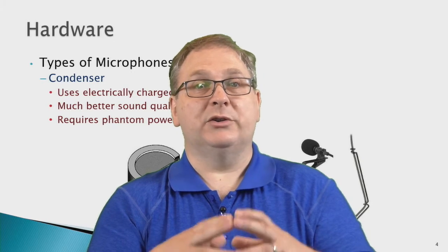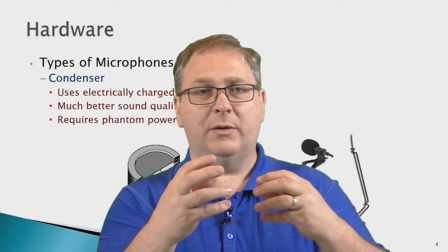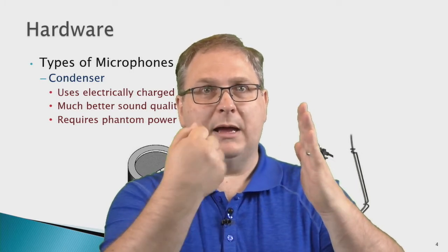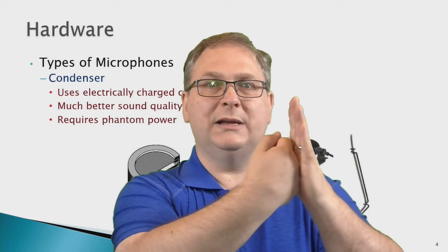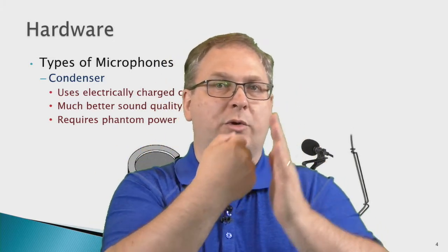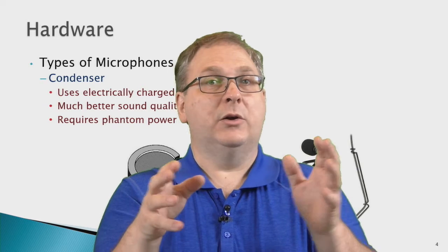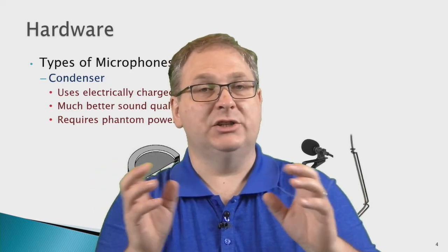This has a better sound quality, and the reason is that if you compare it to a dynamic microphone where you have a magnet, if you have a magnet and metal and you put the two together, they kind of stick, and it takes some force to pull it apart. And so they're always kind of fighting with each other. And so that causes it to not have so much of a linear response. So it works well in the middle frequencies, but the high frequencies and low frequencies tend to have a little bit of change in them.